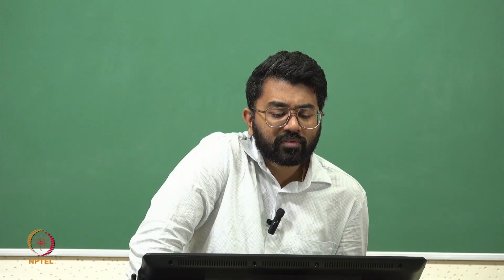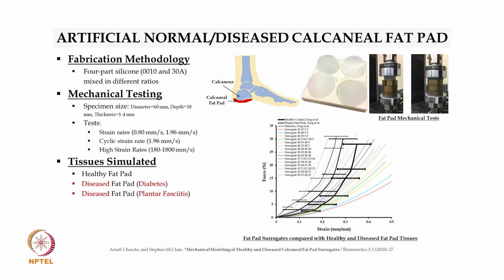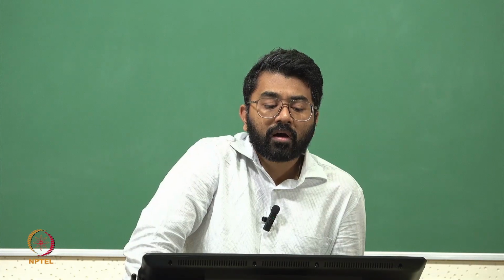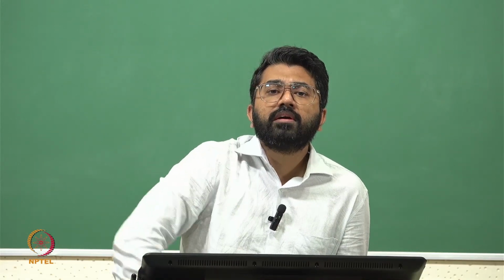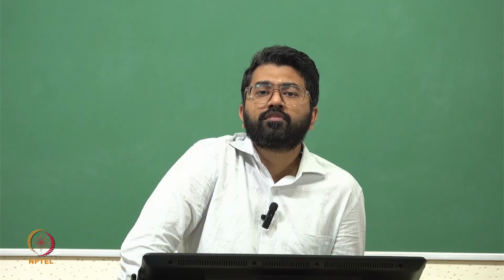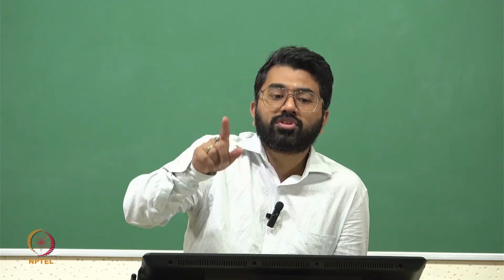So with this motivation we started developing the calcaneal fat pad simulant. Here the fabrication methodology was very similar to the other soft simulants. We looked at 4-part silicone, which has worked pretty well for us for most soft tissue mimicking, because it provides a range of very soft properties to very high stiffness properties, and also has a clearly elastic and hyperelastic response with a highly nonlinear touch, right?